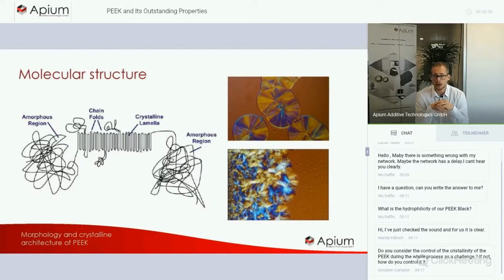And on the image below we can see a heterogeneous crystallization growth, where we have already a site where crystals have been formed before, and then the next crystals will start to crystallize on these already existing surfaces because it takes less energy. And this is something we see also within our crystallization process when we deposit always a new molten layer on an already existing surface.